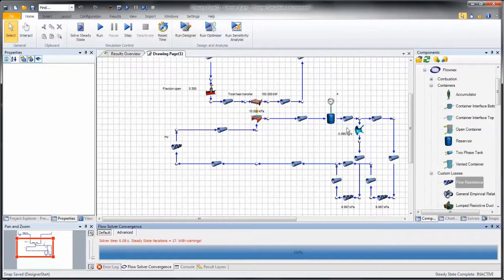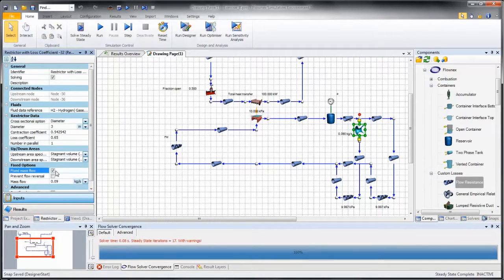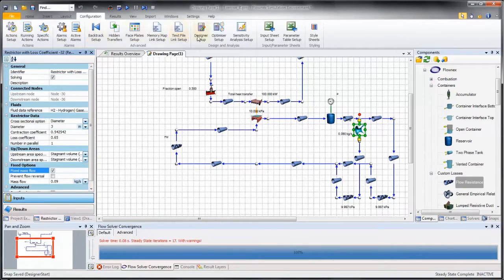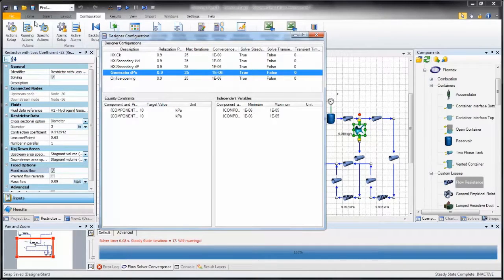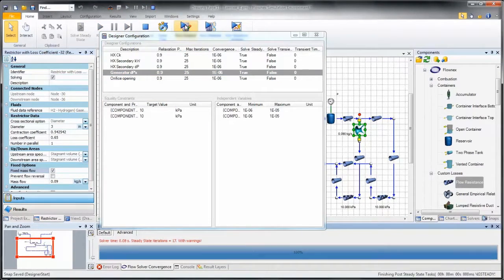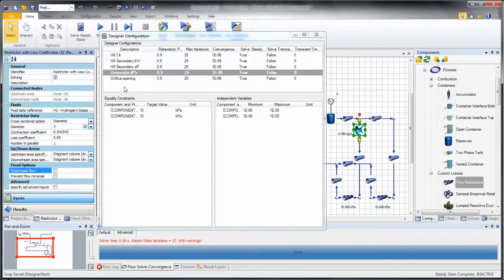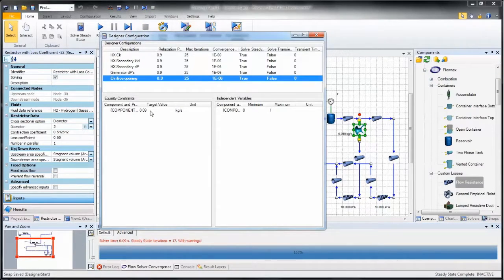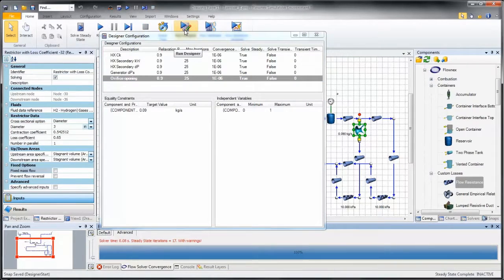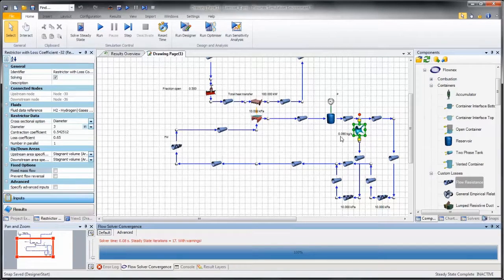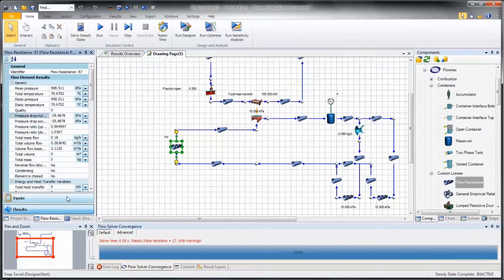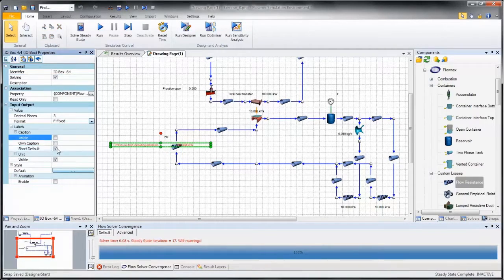For the generator section, I'll just install my trusted valve operator and calibrate my generator losses at the design flow. And finally, I can finish this off by obtaining the actual flow area ratio required for a perfect match of flows. Spot on. And for interest's sake, if I were to design some kind of fan or compressor, I would need a pressure rise of approximately 36 kPa at my design flow.